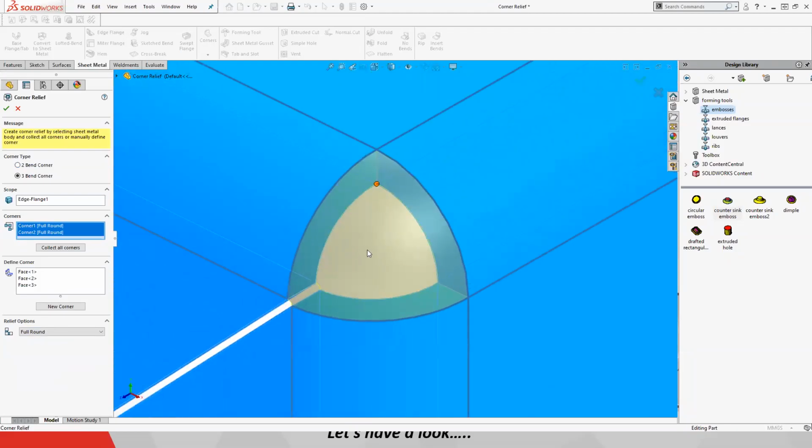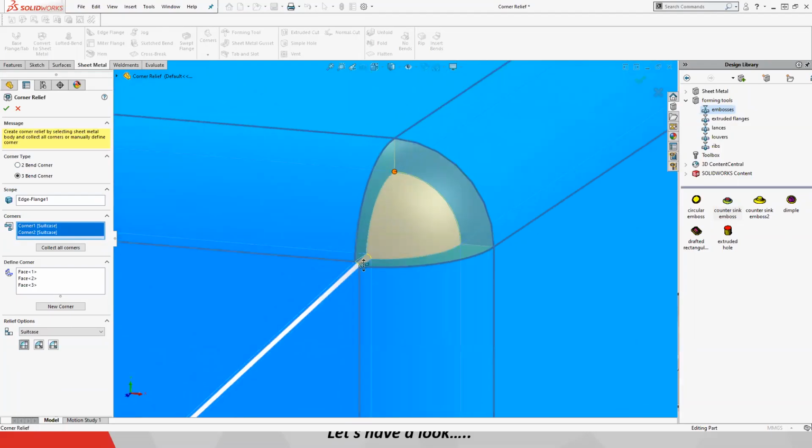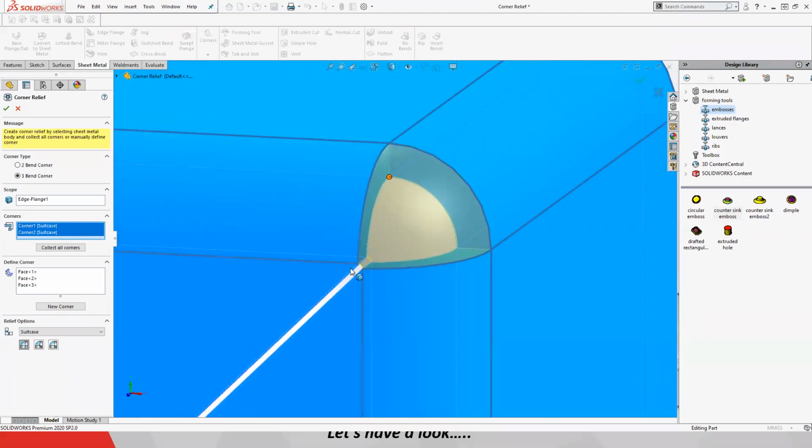As it said, the full round option basically starts at the vertex and then follows the actual opposing edge till it meets the bottom side over there. So it's basically just a nice little closed loft. And then the suitcase option, on the other hand, gives me just a bit more flexibility as to what I can do with this actual cut or extend over there.